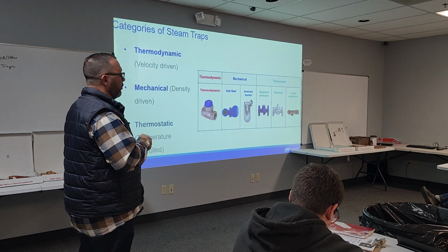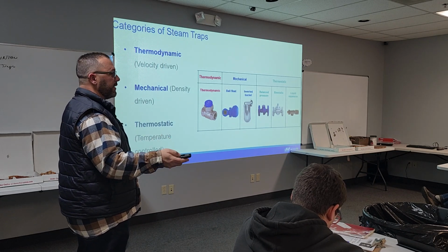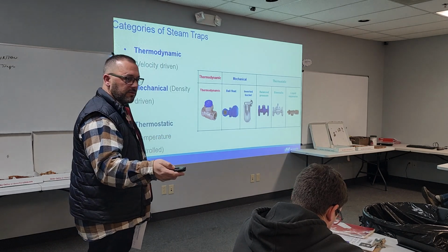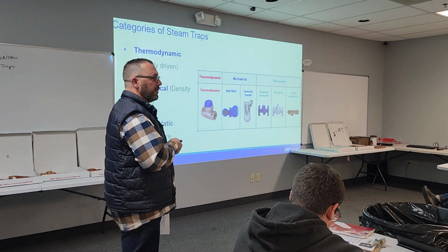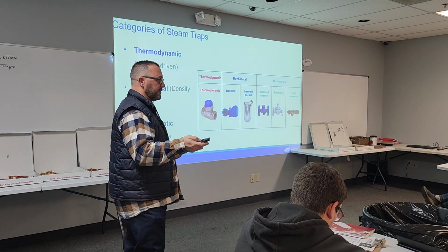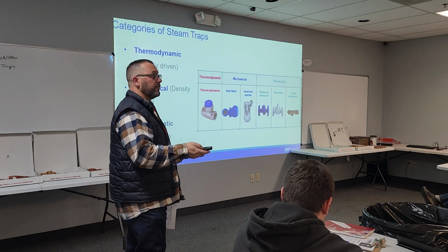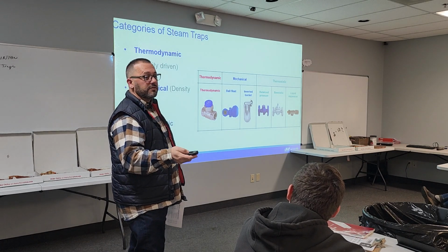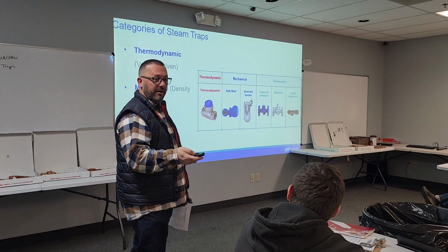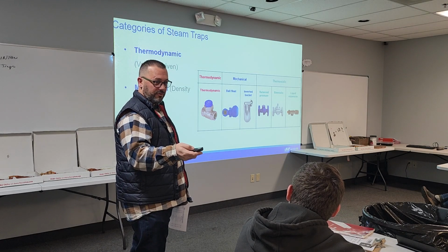One of the other manufacturers has the cheaper thermostatic air vents on the low pressure traps, because when we talk about an F&T trap and a bucket, that's dependent on pressure. F&Ts are made in 15-pound, 30-pound, 75-pound, 125-pound, and 200-pound versions.